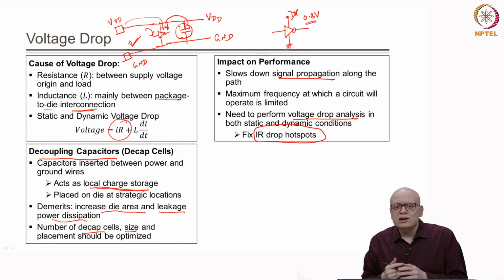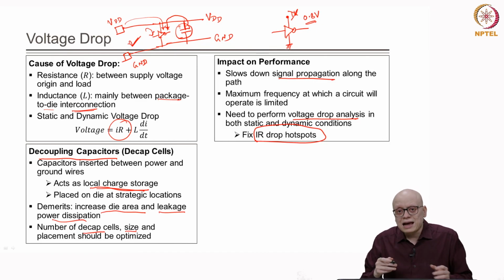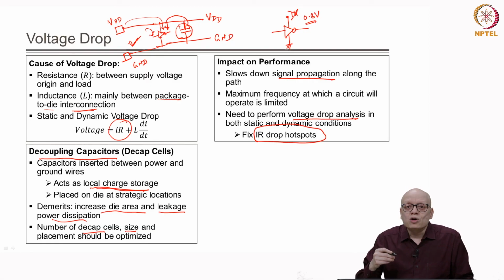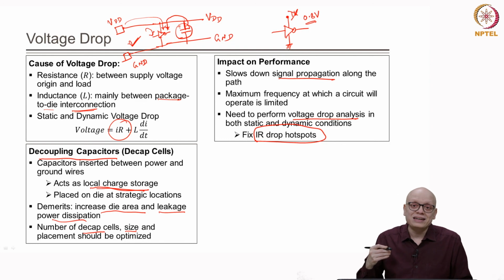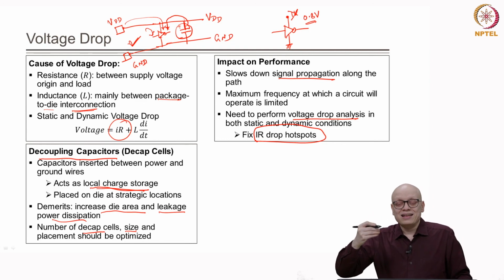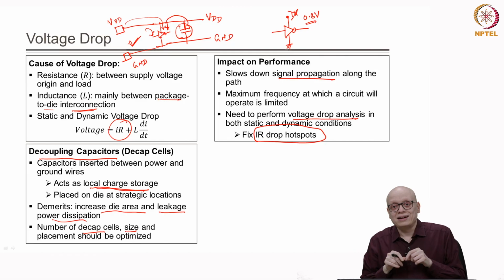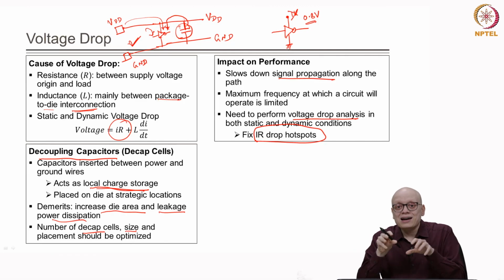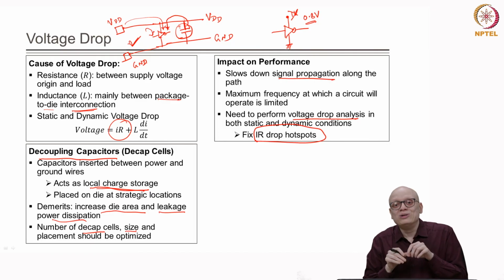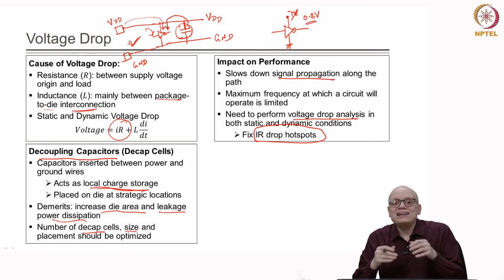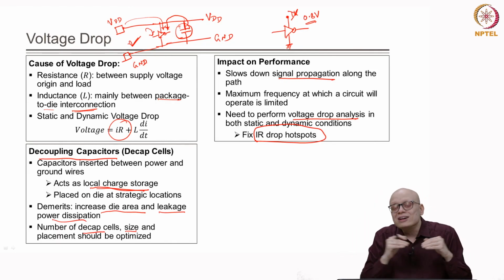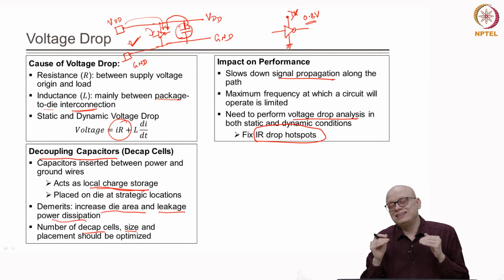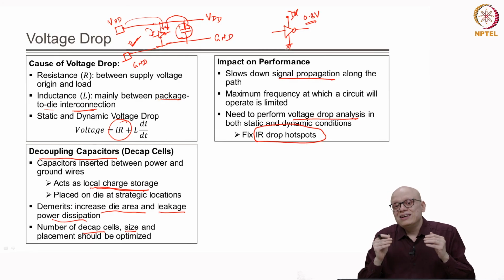Now, the IR drop problem can actually be tackled throughout the VLSI design flow. We can even take decisions at the system level: if in our design there are two modules which are drawing a lot of current, we should power on those modules in a staggered manner, so that the peak current of the circuit comes down and the effective IR drop seen by the circuit is reduced.